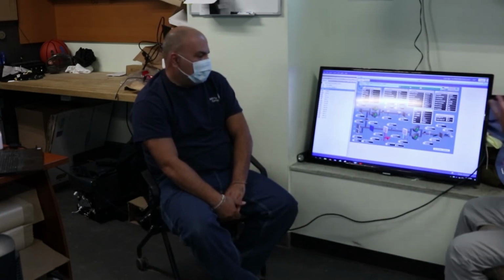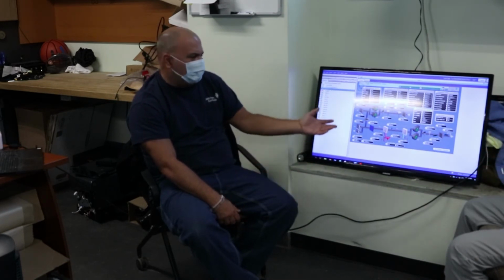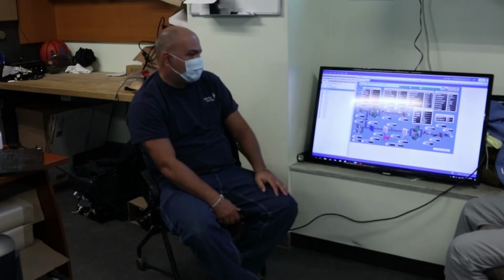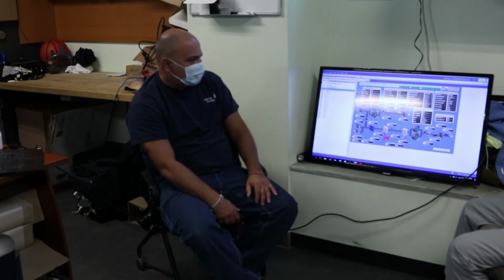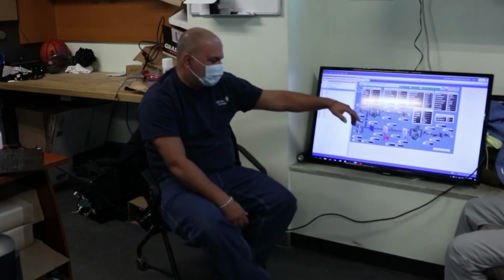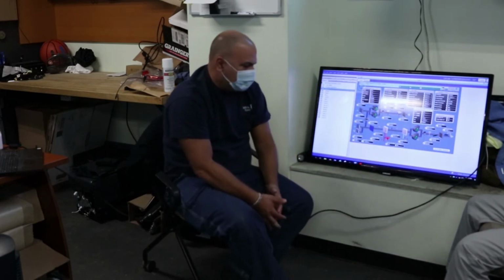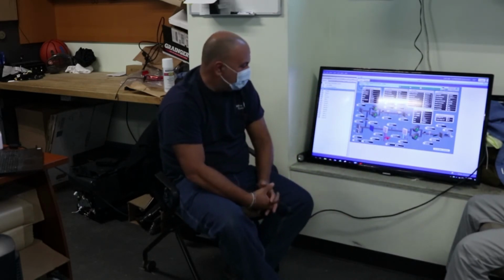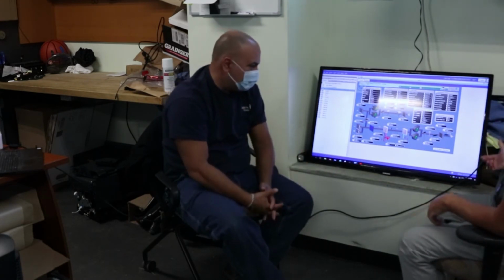I think it comes off the status of the chill water pumps. If you don't have any pumps running, you don't have any cooling. I didn't do that, but that's usually where they take it off of, the chiller pumps. They can also make it based on when the chill water is below a certain setting.